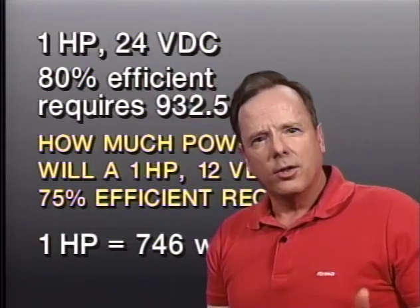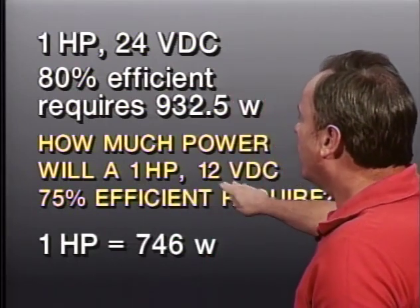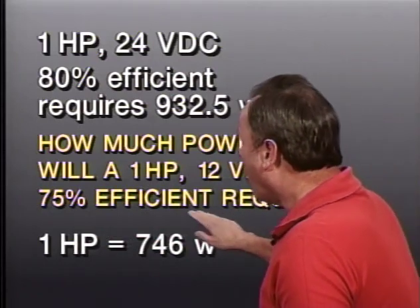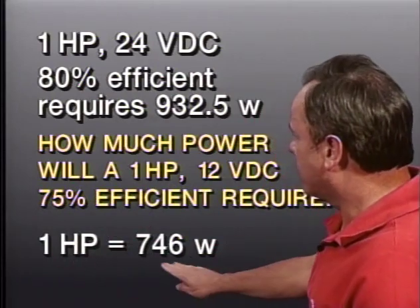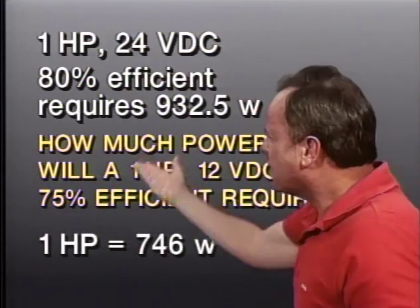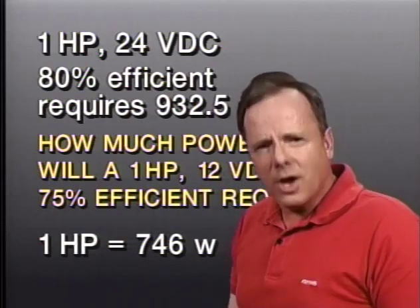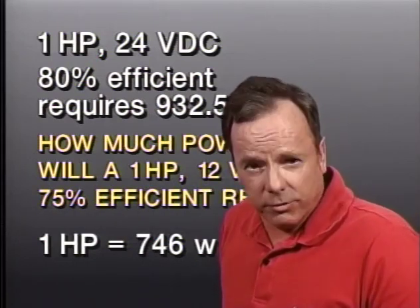Then they ask you this question. They're going to ask you, how much power will a 1 horsepower, 12-volt DC electric motor require if it's 75% efficient? How much horsepower or watts will be required to produce that 1 horsepower? And they also tell you that 1 horsepower equals 746 watts. Now you might look at this and say, well, hold it, wait a minute. What does this top part have to do with this question? I've got the information I need right here, don't I? And the answer is, this top part had absolutely nothing to do with the question. They just threw that in there to confuse you.